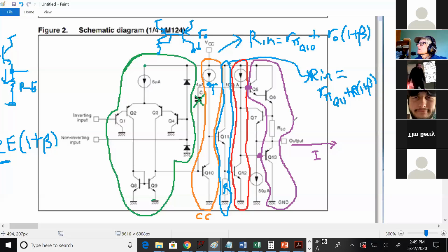If you were using diodes that had a magic perfect VBE on voltage, where might you put them to get rid of the crossover distortion? You could throw them in between those two bases, right? Yeah, that delays the turn on of the other pair until you're past that voltage.